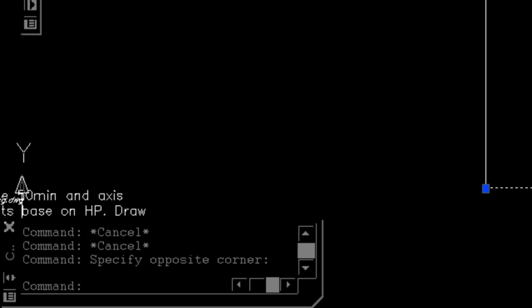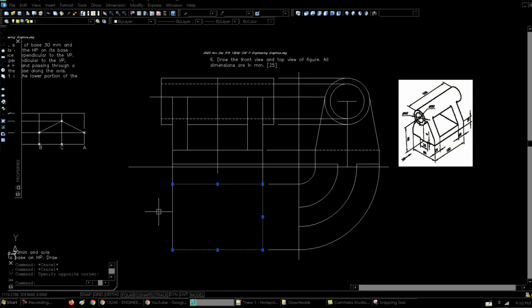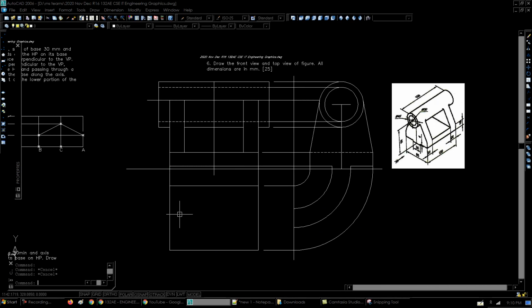Now the cylinder is going to be appearing on top of this. So cylinder is going to be appearing on top of this, and we're supposed to draw the cylinder. We'll have to take vertical line from the quadrants, and then we'll have to transfer this distance to the horizontal edge, and then I'll have to draw these lines over here.